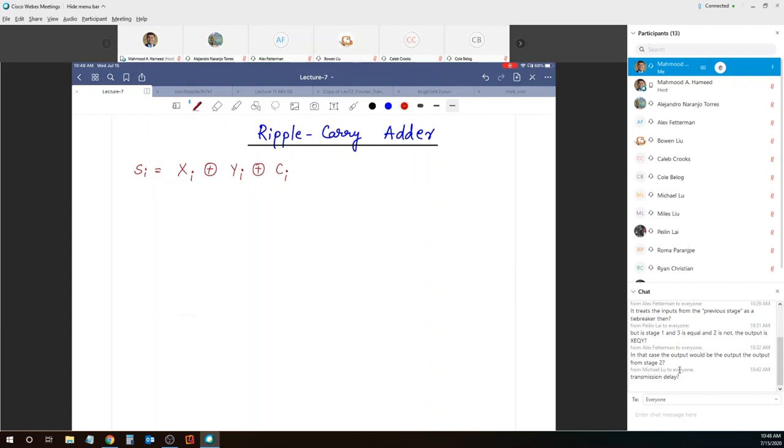And you can verify this later on whether this is actually correct or not. Sum at the ith position is related to the numbers and also to the carry. I do not need to wait for the numbers. Those are readily available to me. But I need to wait for the carry, which is the bottleneck.